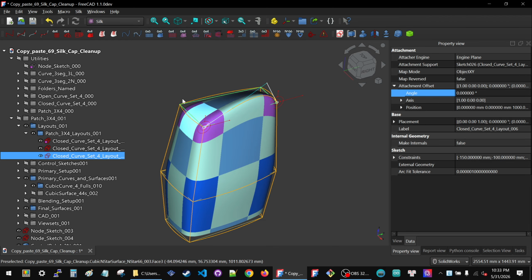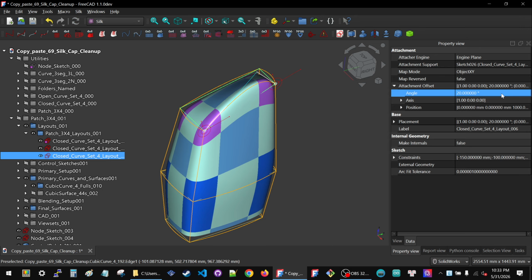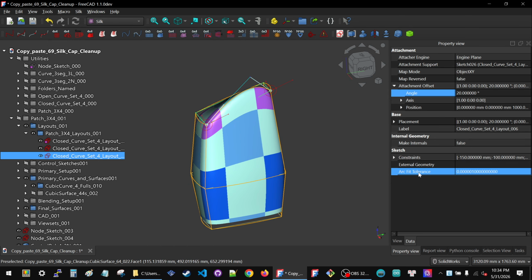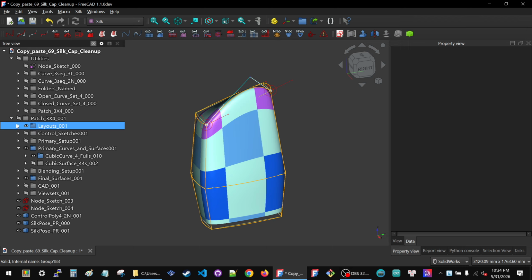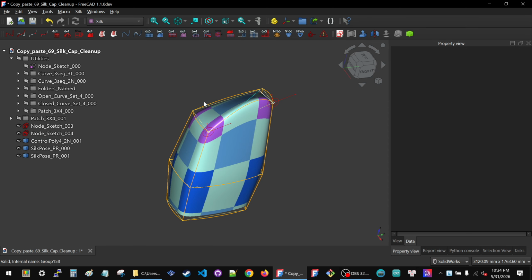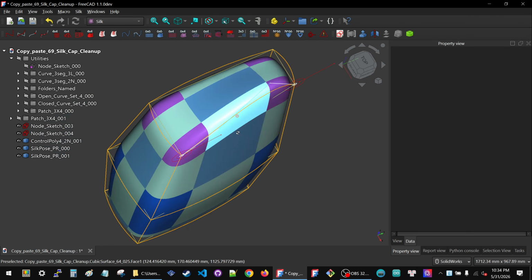But you see, as soon as I made this layout not have a crazy rotation, most of the problems went away. And we can have a little bit of rotation. Let's do something sensible, like 20 degrees. This is not crazy. See, if I do 20 degrees on top, this blend is not busted, and now I can do what I call 3D sculpting, which means that I'm manipulating 3D curves to change this shape.